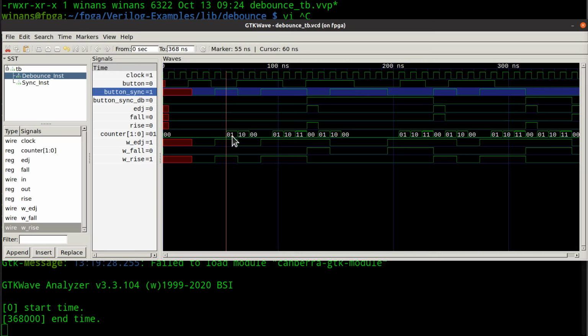Okay, and we want to count up to 4 minus 1, because 0 counts as one of the values. 0, 1, 2, 3, and then we have an output, and you can see there's a 3 right there, okay, in binary. All right, so he's high. We got a rising edge. Great. Let's move on. Over here, another rising edge on the clock is true, and it sees that input as a 1. He advances it to a 2.